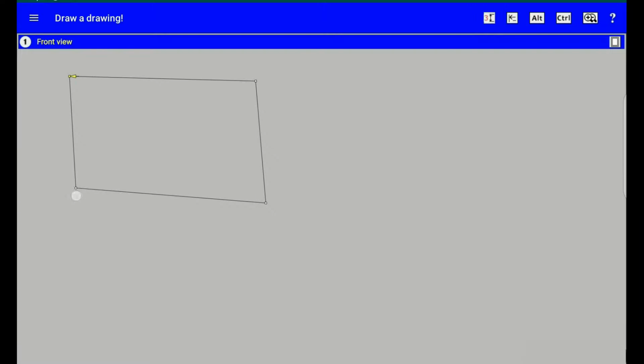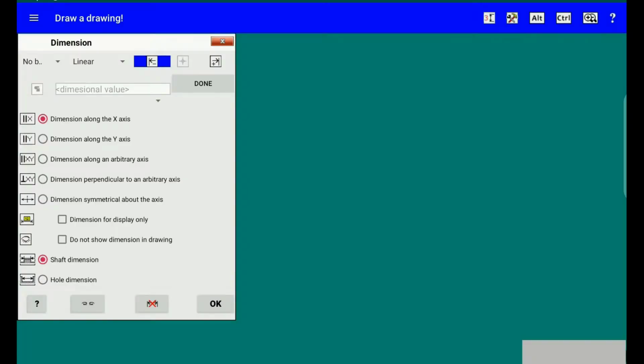I marked 2 points at once for the same dimension. This means that these points will be set on the projection plane along the same vertical extension line, which is the support of the entered dimension. Now for the linear dimension we put an outrigger with large coordinates along the x-axis. Please note that the Done button of the Dimension Input Control dialog has become available, but it is too early to use it, since the dimension has not been fully entered yet. Exit the dialog by clicking the OK button.